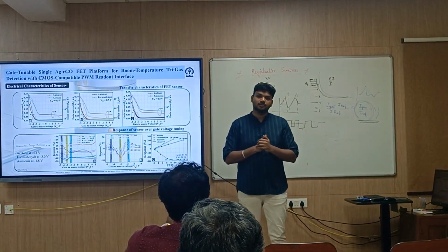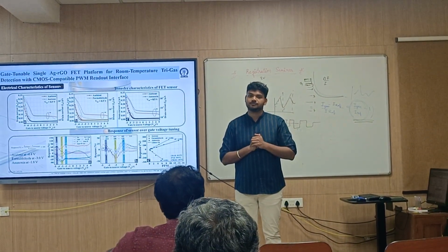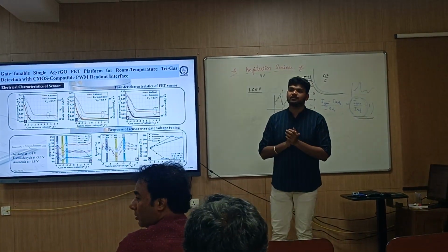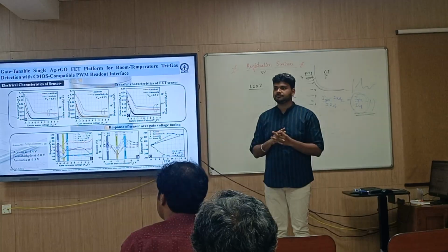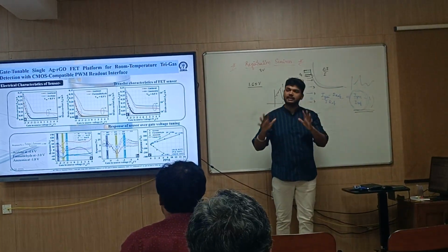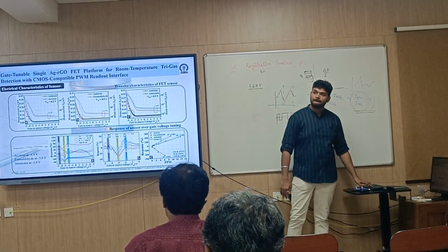No, you have to introduce delay. Manual delay you need to introduce and then check how it is affected. Overlapping. The recovery time is normally slower than the response time. That's why I just fill the chamber and then take the reading. Please make a detailed study on the ramp.